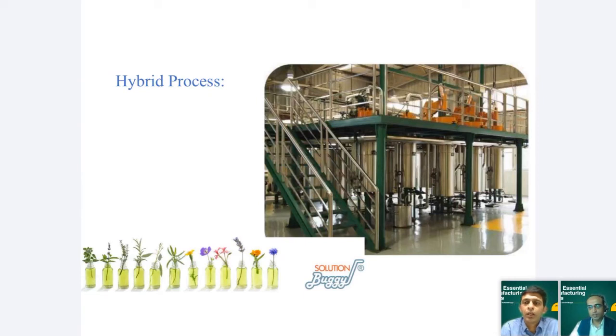And there is a question saying that if I'm using ethanol as a solvent in one of the extraction processes, do I need any specific clearances? Yes. First of all, for using ethanol, you need to have a specific quota from the government. Ethanol is government controlled, and to get a quota, you have to apply for an ethanol use license, which is easily possible if you explain the process. Second, you will require proper setup where the ethanol is being used.